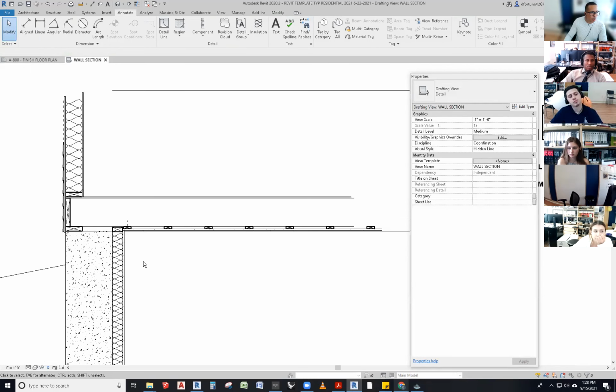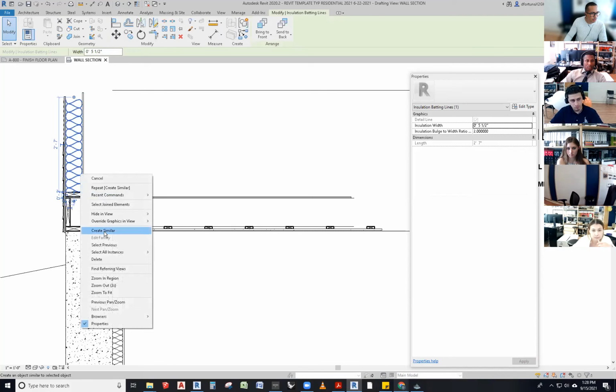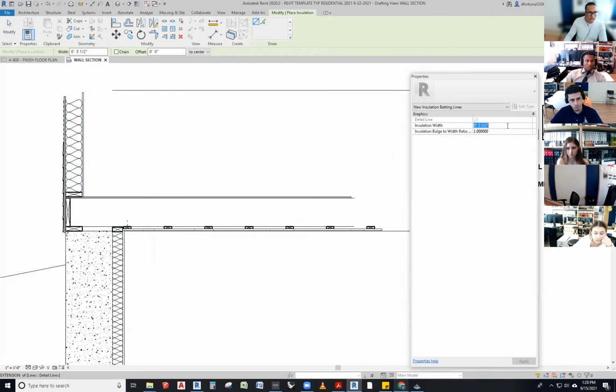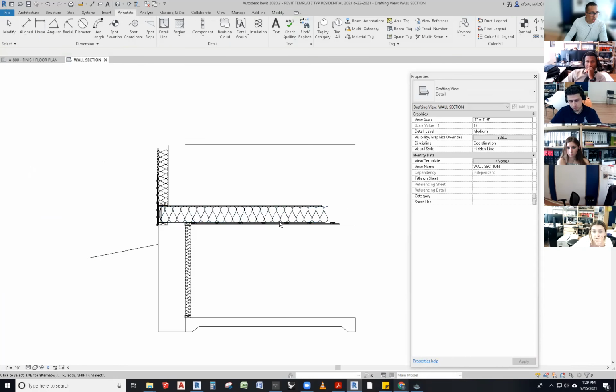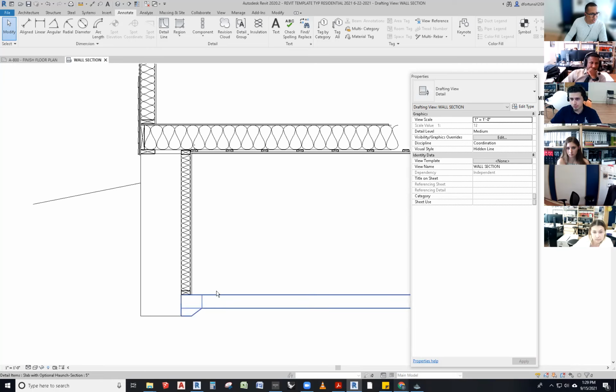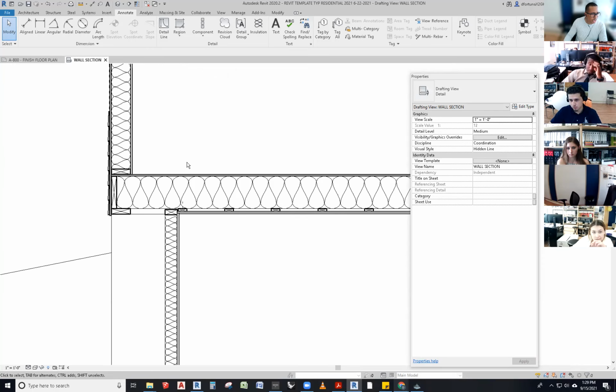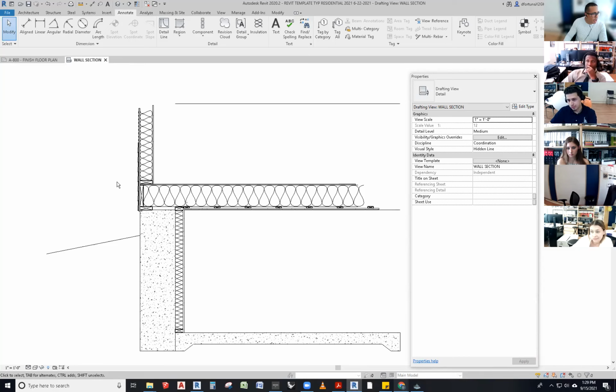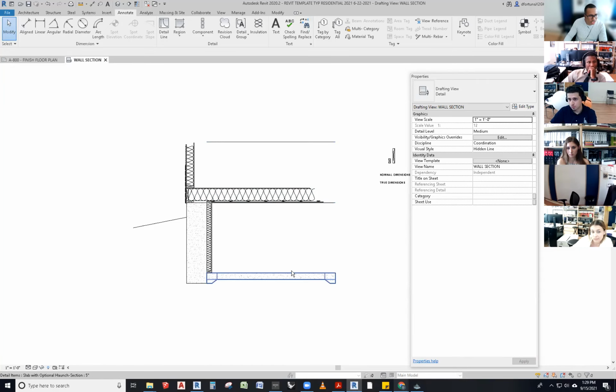Okay, what else are we missing? Insulation inside this space. Yes, we put insulation from the ceiling of the basement to the other one, and that will be made out of, instead of 5.5 or 3.5, 9.25 because we're using 2x10s. Great. We have right now a finished space. It's just missing a finished flooring, another finished flooring in here. But this is the basic for that condition right here.